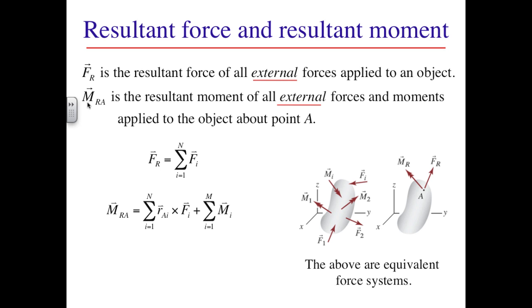This may seem contradictory given that we just stated we can't pick forces up off their original lines of action. But the displacement of forces from those original lines of action influences the rotational behavior, and that shows up in the resultant moment. The displacement of forces from those original lines of action does not affect the translational behavior, so they can be combined into a resultant force. The resultant moment is the sum of two sets of terms.